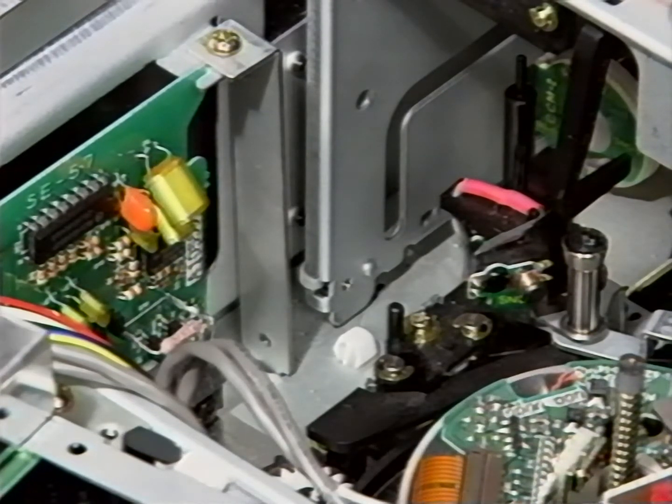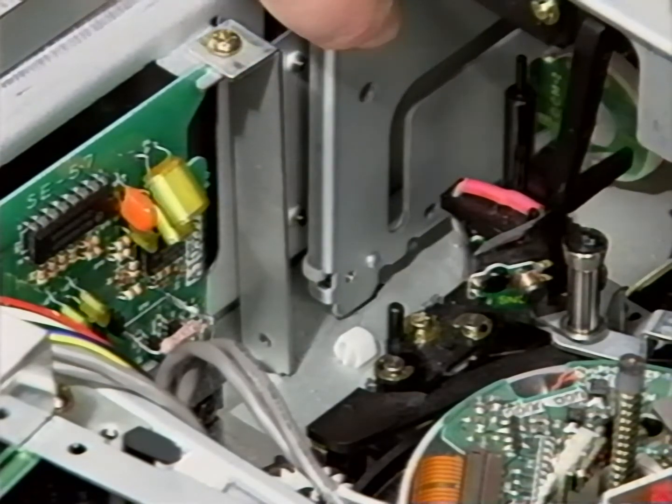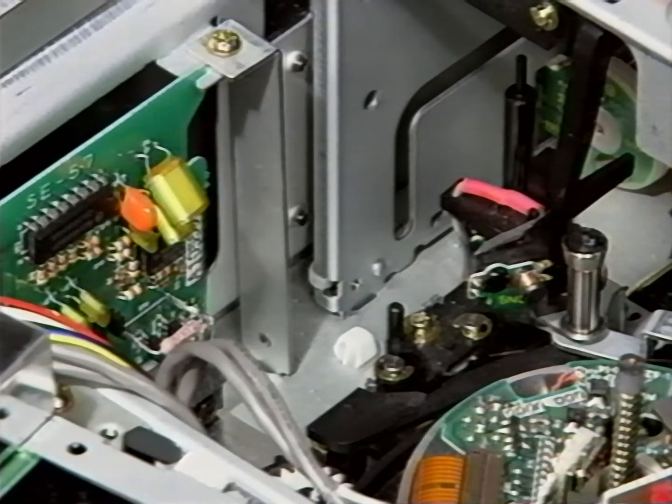Error 1 through 4 are concerned with tape slack, tape spillage, and tape damage. It is even possible to bend the cassette compartment if it is incorrectly inserted and the cassette compartment stay bar is tightened down. If this happens, the cassette compartment will probably have to be replaced.